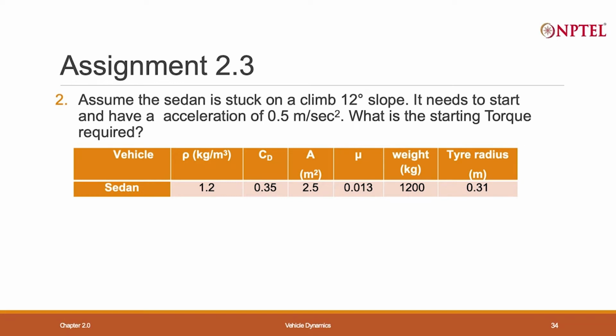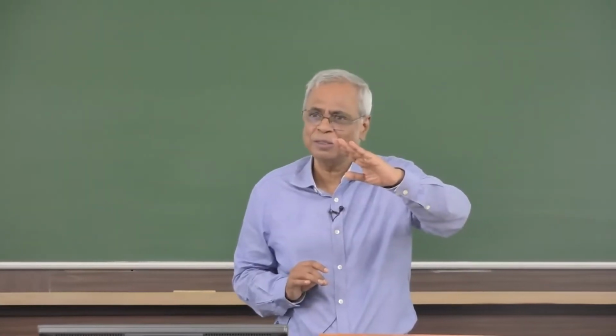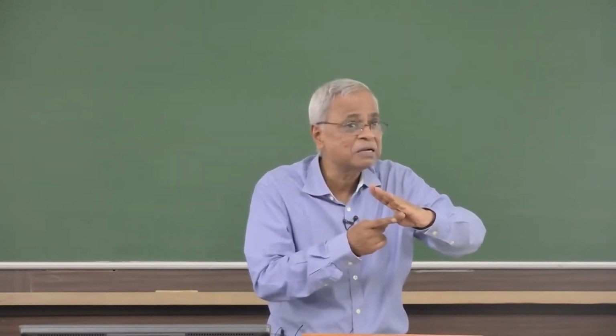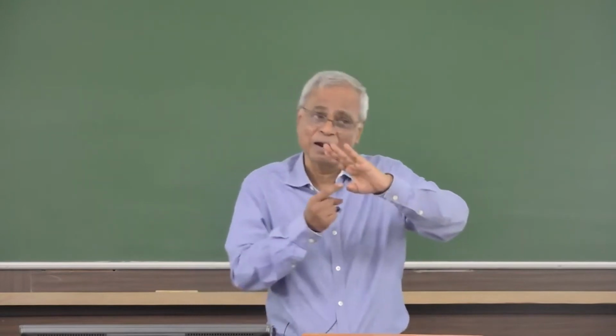When it is stuck, it has to start, and during a start it will require a torque, plus I will have to give a minimum acceleration for it to get moving. I have taken a very small acceleration, 0.5 meter per second square. So, now what do I have to do? For that vehicle at 0 speed I have to worry about the torque, then I have to worry about the acceleration and torque due to acceleration, plus there is a drag force, I have to worry about the drag